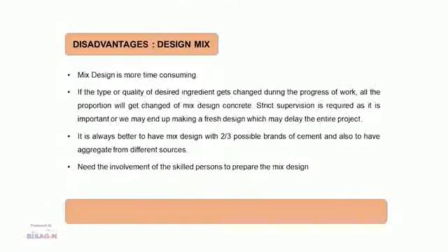Now, disadvantages of design mix. Mix design is more time consuming. If the type or quality of the desired ingredient gets changed during the process of work, all the proportions of the mix design concrete will get changed. Strict supervision is required, or we may end up making a fresh design which may delay the entire project. It is always better to have a mix design with 2 or 3 possible brands of cement, and also to have aggregate from different sources. And last, it needs the involvement of a skilled person to prepare the mix design.